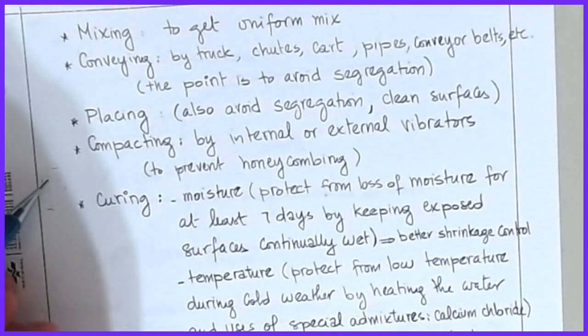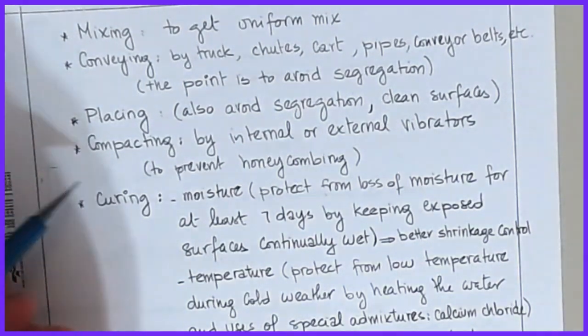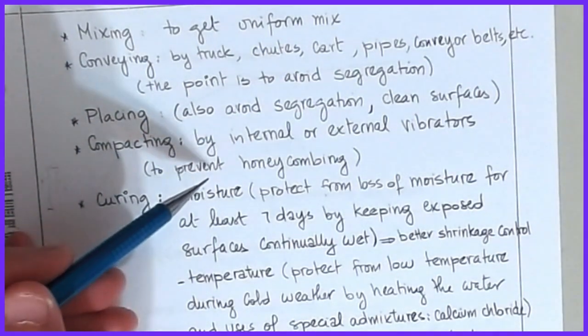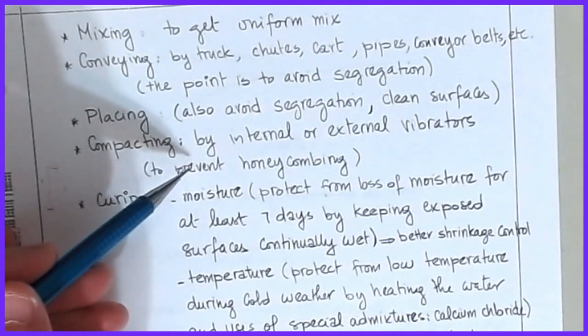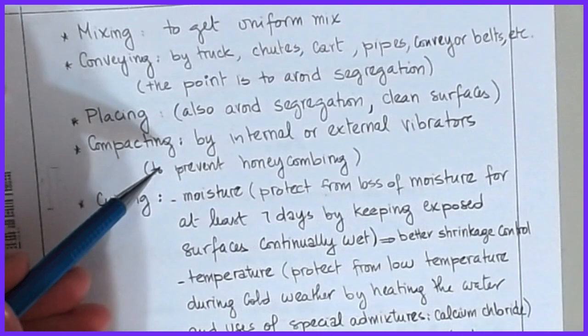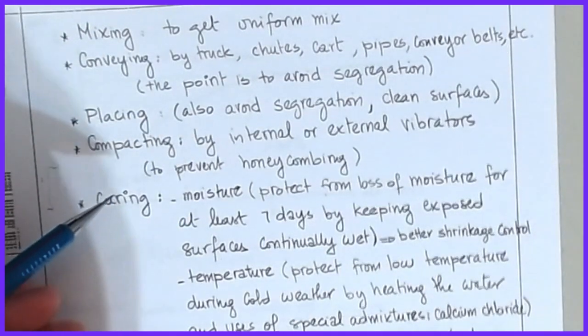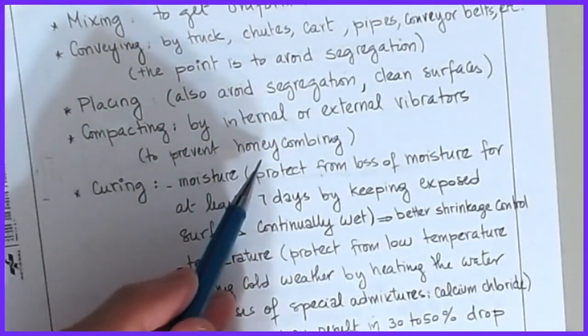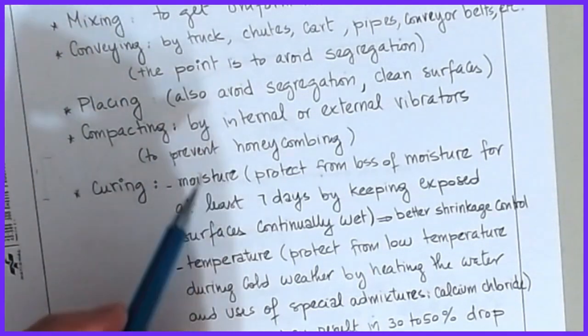But it does help significantly with preventing what we call honeycombing, which is the entrapment of air pockets. You take the forms off and you have these big air voids in there. It looks like a honeycomb pattern in spots. And that's our goal, to prevent that, because that also affects our strength distribution.